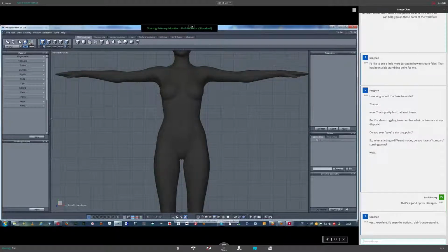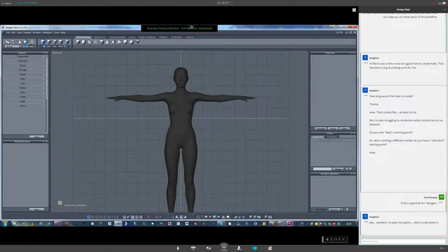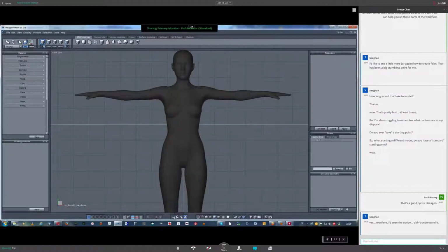Now I'm going to change my view mode to front view, because that will make it a bit easier for me to position my cylinder. I'm going here to the 3D primitives and select this cylinder. I'm using the first anchor point, her navel, which is roughly in the middle of my scene. Click, drag once. That's for you to determine the diameter of your cylinder. Click another time and then draw up or down, and this determines the height of your cylinder.